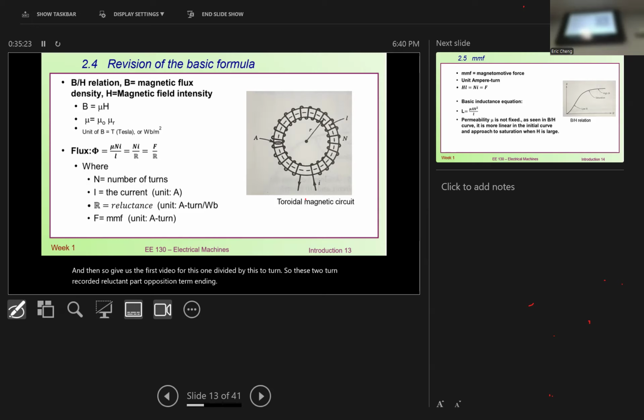Yes. Does the mu in the equation represent micro, or I believe in physics there was a magnetic dipole moment? We don't go through that one. The mu is called the permeability. Permeability is how the magnetic flux flows in our atmosphere. So that's why you can see that the mu has two components. Combined together we call it permeability. But actually we try to relate them to the natural permeability, which is mu naught, 4 pi times 10 to the -7. If an iron core, it can be 5,000. So it depends on which material you use.